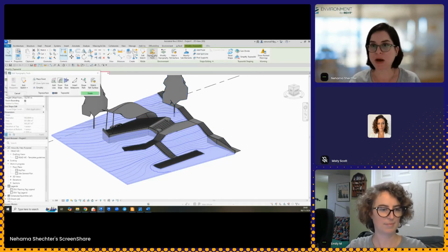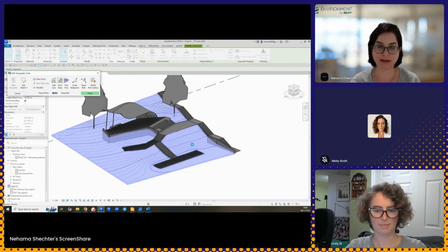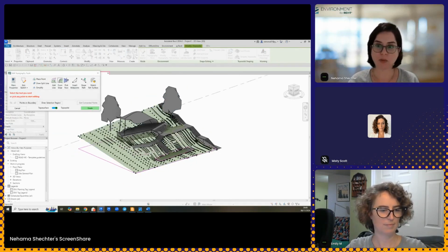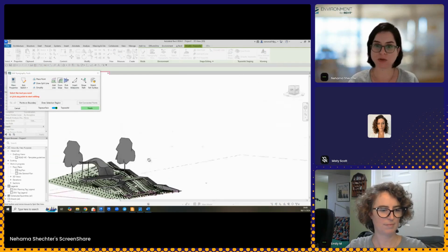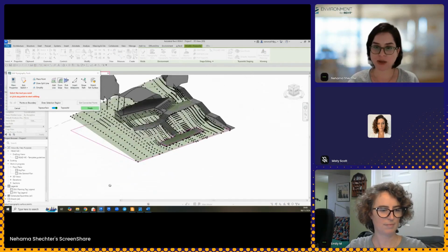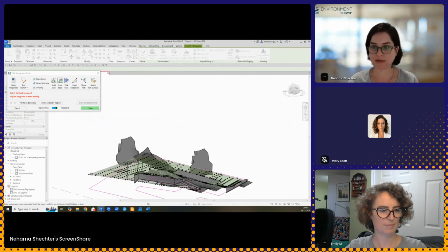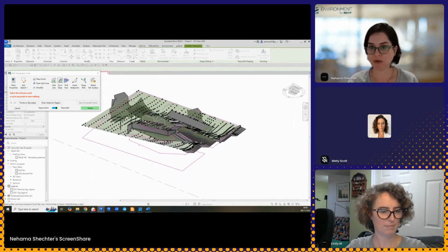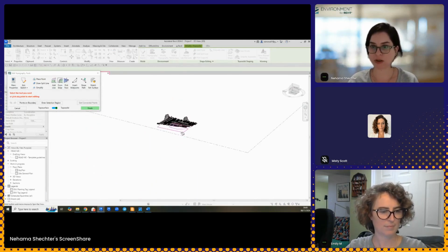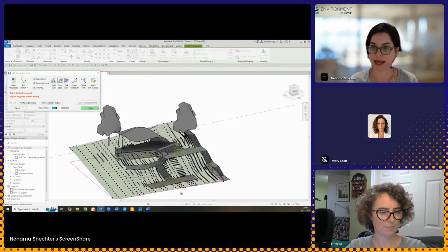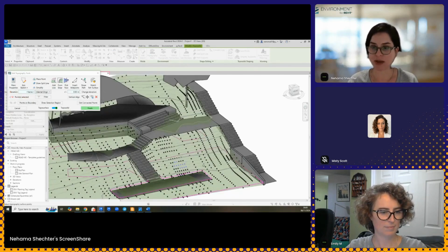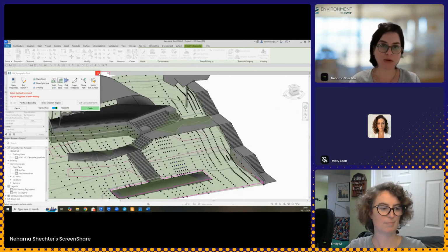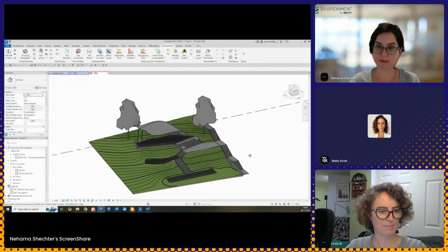So now I'm actually able to have a genuine native Revit toposolid. And what's nice about it is that I can actually now edit that. And when I'm editing the toposolid with Environment topography tools, you can see in pink over here, you can actually see the boundary, the true boundary that came from Rhino and the elevation points. And each of them is editable, both the boundary and the elevation points.